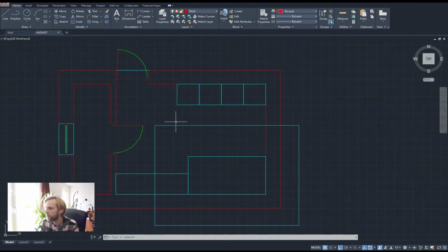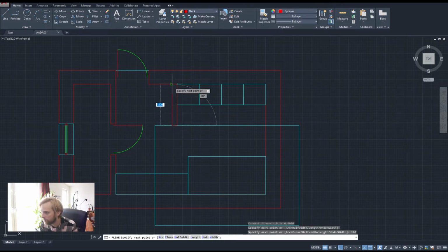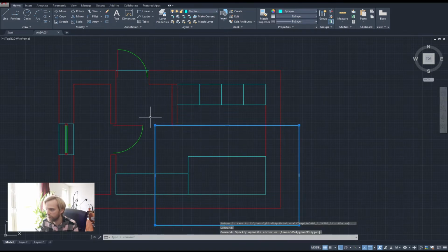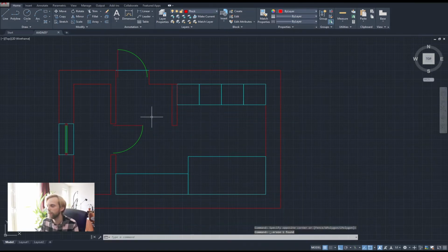So now I know that the longest wall that I can have is something like this, right? In the gap between here, I will create a polyline now, draw it out like so. I'll give it 140 millimeters to the side and finish it up here. And now I don't need the helper line anymore, so I can delete it.